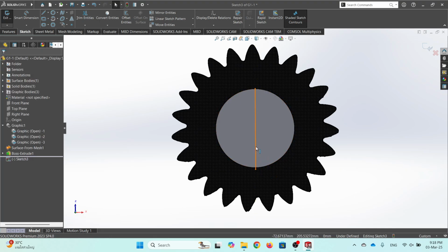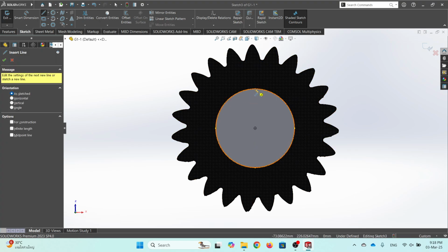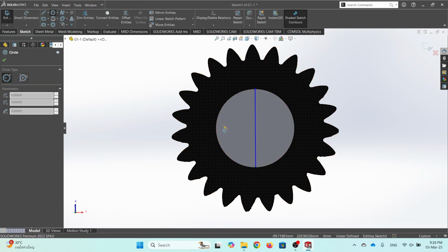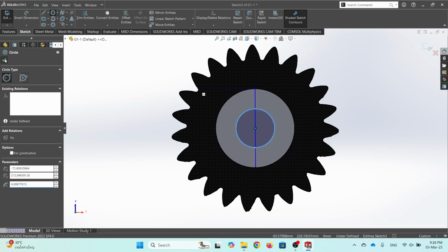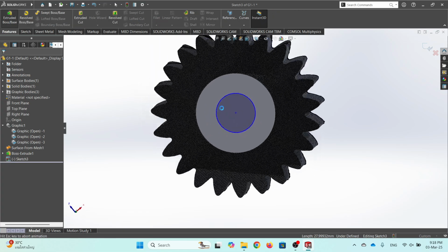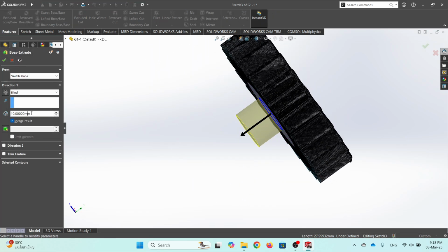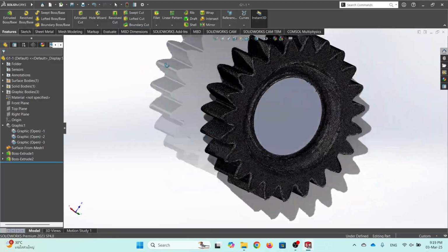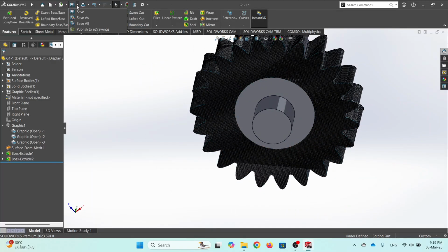And let's do that again, up here along the edges, and then we're gonna draw the circle exactly in the middle, and the radius right here you can design by yourself. And let's extrude this as a pin outward. So let's say around 10 millimeters is fine, right? And then you are finished with the first part, and then we're gonna save it.